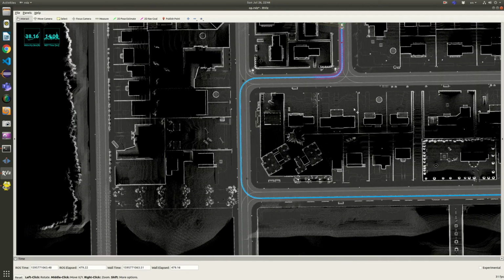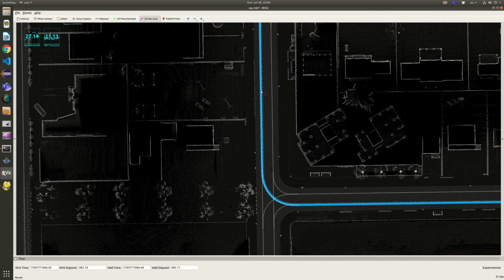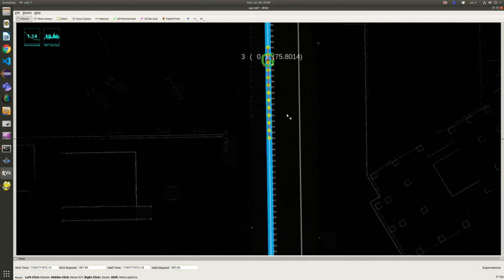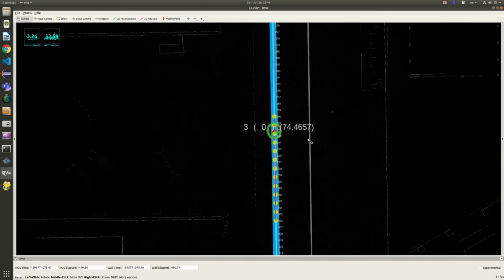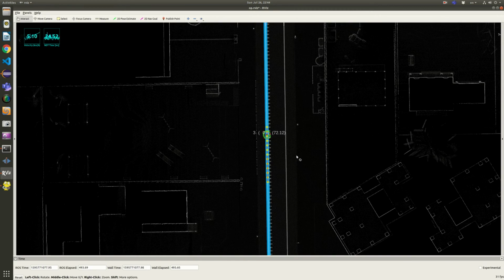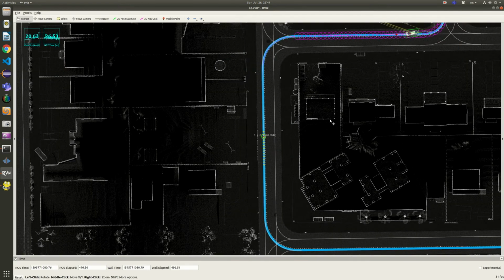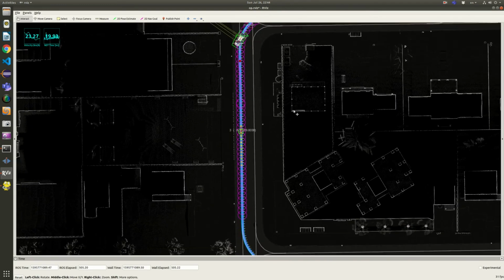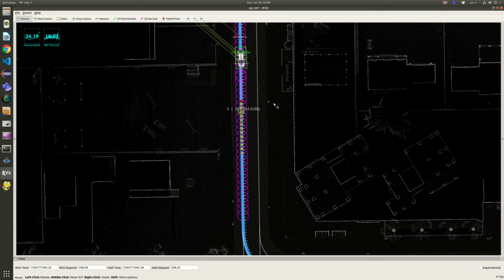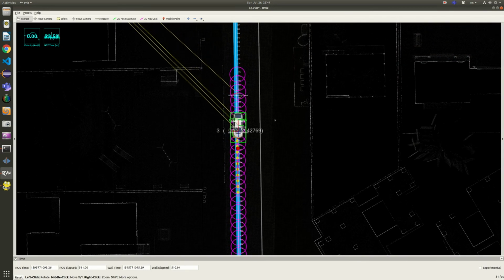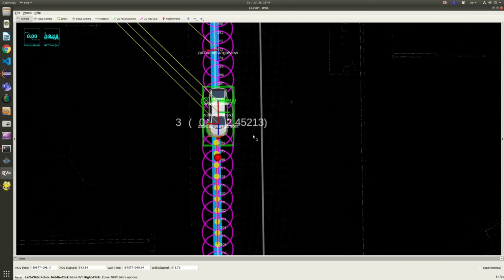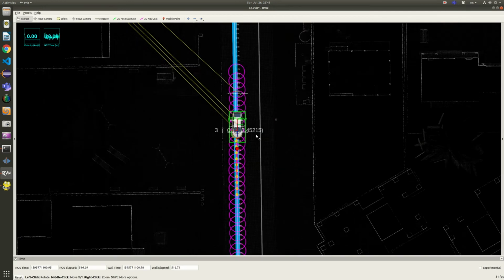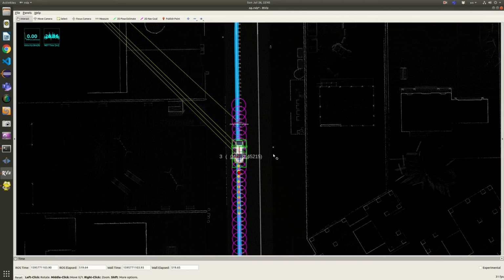Then I want to put it in another place, for example here. So now I inserted an obstacle here. Because it's on the lane, the motion prediction thinks that it's a vehicle, so this is the estimated trajectory for this vehicle. Now the vehicle is coming close, it detects, goes into follow mode, and then hits the obstacle. Okay, it didn't brake early enough.